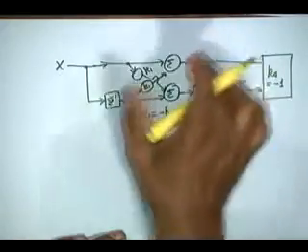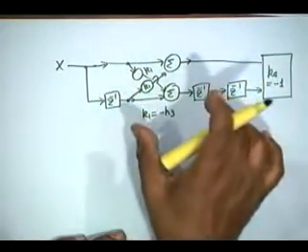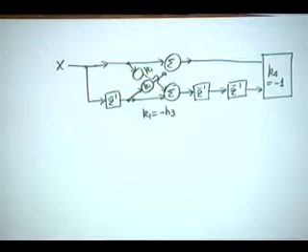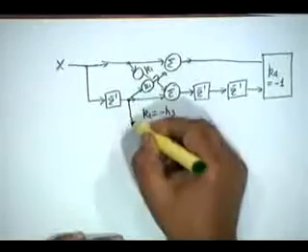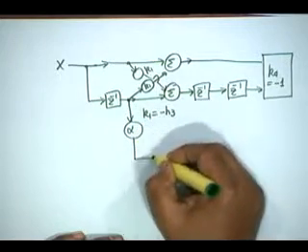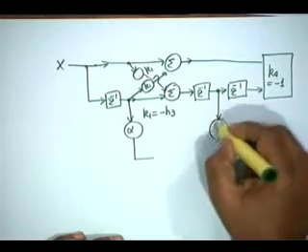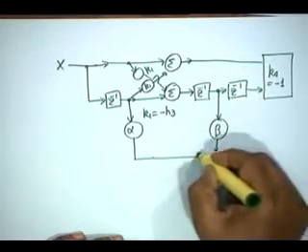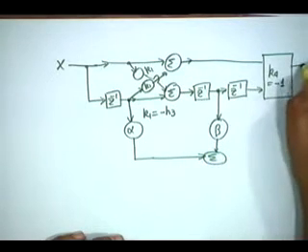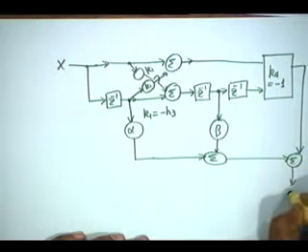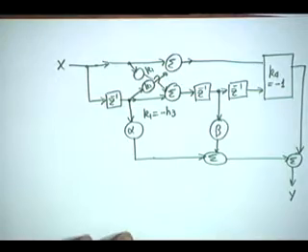So everything is done except that we have to take now 2 tappings. You see, we have synthesized the linear phase transfer function by observation, because from 4 it has dropped to 1 because of the anti-symmetry. If it was symmetry, then from 4 it comes to 2. Okay. So I have to use 2 taps. Let us say this is alpha and another here, z to the minus 2. Let us say this is beta, and add with this. The only thing that remains to be found are the values of alpha and beta.